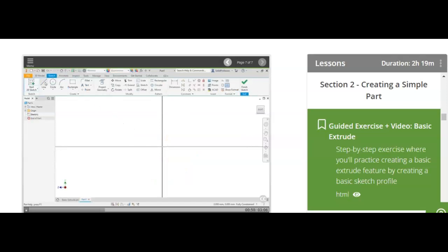I will select the line tool and begin the first endpoint on the origin. I'll sketch the vertical and horizontal lines. The next thing I will need here is an arc. You could use any of the various arc tools in the Create panel, but since this arc will be tangent to this endpoint here, I prefer to use Auto Transition.